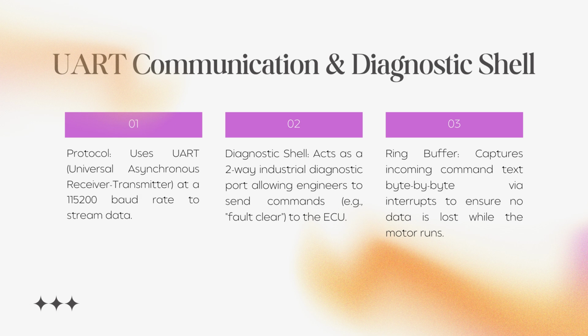Because commands arrive randomly, we use a UART interrupt tied to a ring buffer. This safely stores incoming letters byte by byte in the background without pausing the motor control. Once a full command like fault clear is received, our shell process validates it and executes the request.